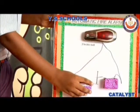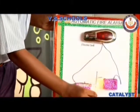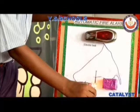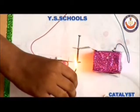Hello everyone, I am Catalyst Rishabjot Singh. I am going to present my project, Automatic Fire Alarm. It is based on the unequal expansion of metals. This is a bimetallic strip. Its downside is brass and its upper side is invar. When we heat the bimetallic strip, the brass expands more than invar. When it touches the screw, it completes the circuit and the bell rings.